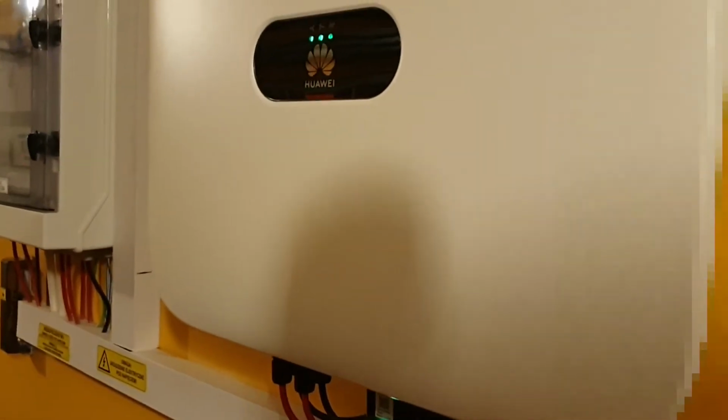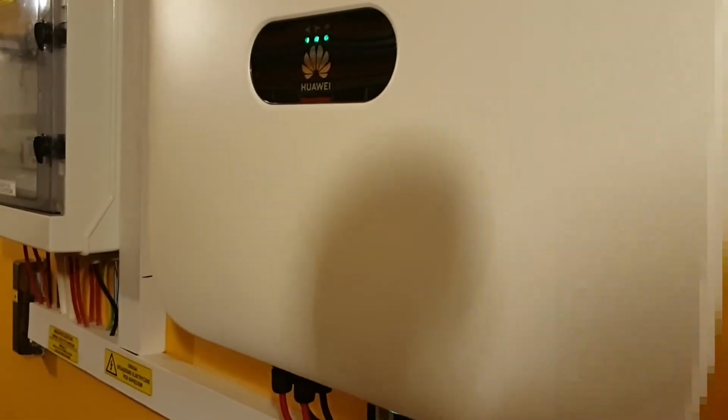So I have it done, and I also used half-cut technology panels. And the half-cut technology panels have that benefit that even if one panel is covered by shadow, some obstacle like, for example, a chimney could project shadow on one half, the other half can operate independently. If it wasn't done in half-cut technology, the whole panel would produce a lower amount of energy.